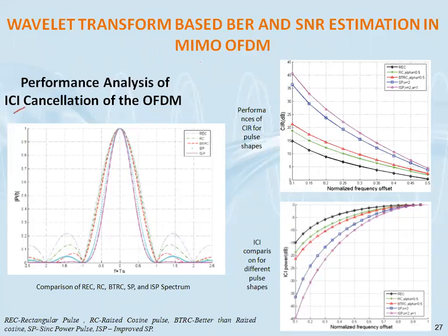That means we'll have the signal that's been transmitted, and those signals are given by n number of carrier signals. We may have hundreds of thousands of carrier signals, whereas these two carrier signals will be orthogonal to each other. The concept of intercarrier interference is one in which the carrier signals themselves may get distorted. The carrier signals are basically the envelopes to carry the signal. Therefore, sometimes the carrier signal itself may get distorted, and once they get distorted, obviously the signal is going to get disturbed.